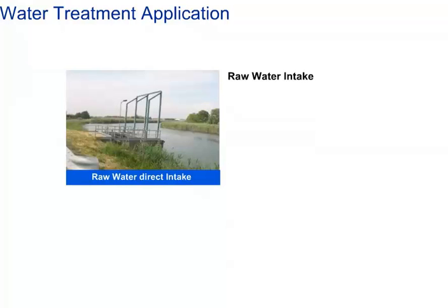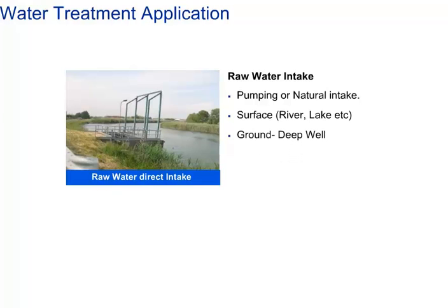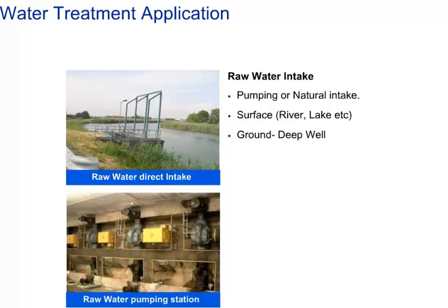There are several sources of raw water that are used in the potable water cycle. Many plants get their water from surface water. Examples of these are rivers, streams, canals, lakes, and reservoirs. They can be locally found or imported over long distances via aqueducts or large pumping stations. Another source of raw water is desalination. In this process, the water is either heated or passed through special filters to remove the salt. It's not unusual to use several different sources making up a plant's intake to reduce the time and chemicals needed to treat the raw water.